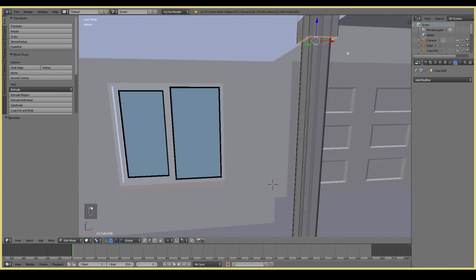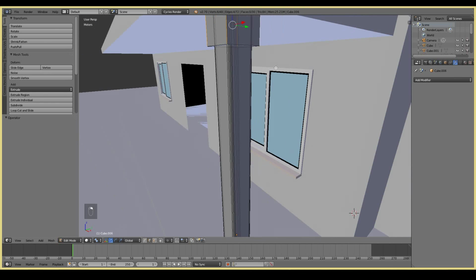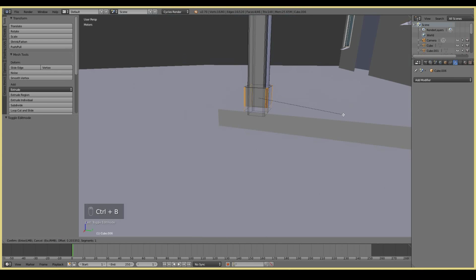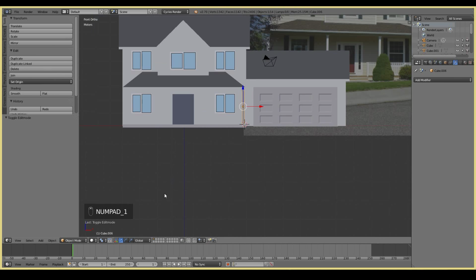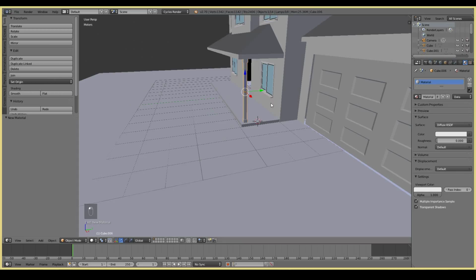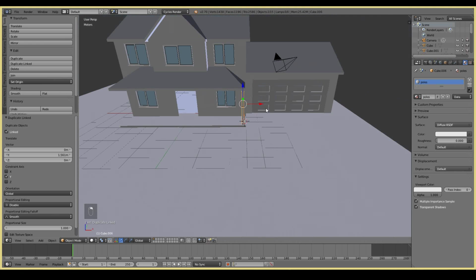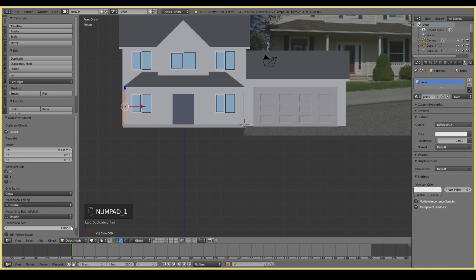Using the reference image, I can see that the edges are relatively smooth, so I go to each corner and smooth it out a little bit. Of course, another way of doing this is adding a subdivision surface, but since I'm going for a low poly model, I don't really want to touch subsurf as much, but I do end up using subsurf anyway on the fence.